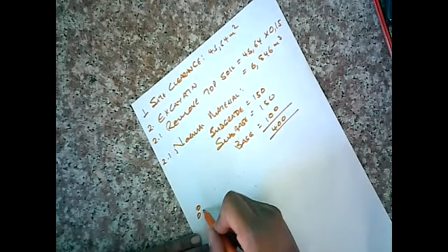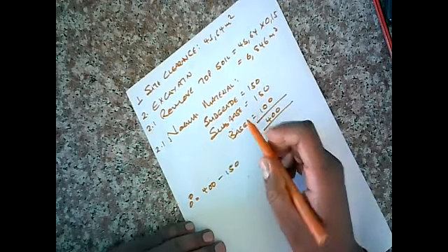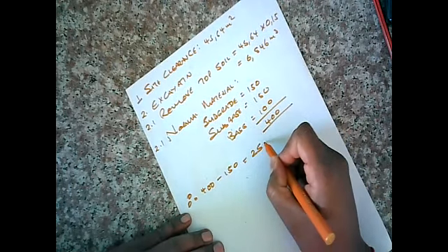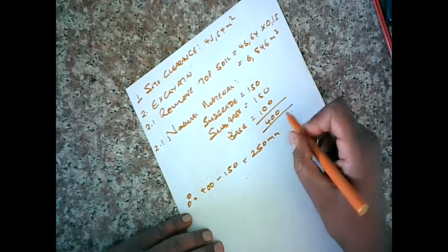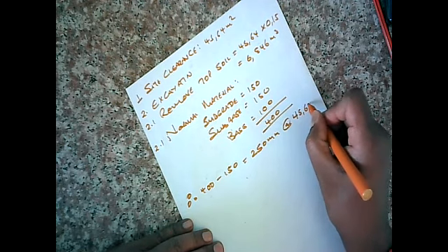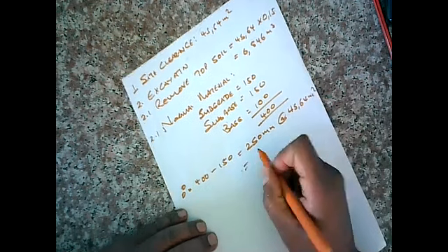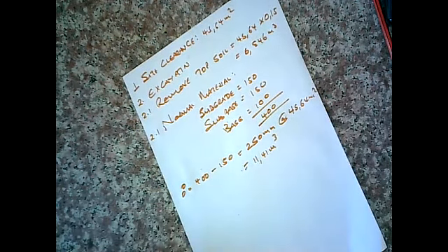Therefore, 400 minus 150 topsoil that we've already taken off, and we've got an effective depth of 250 millimeters at an area of 45.64 meters squared. We've got a total volume of 11.41 meter cube. Right, so we've quantified that.